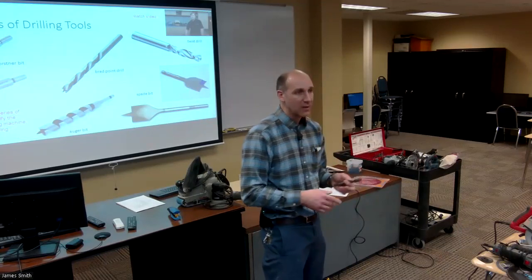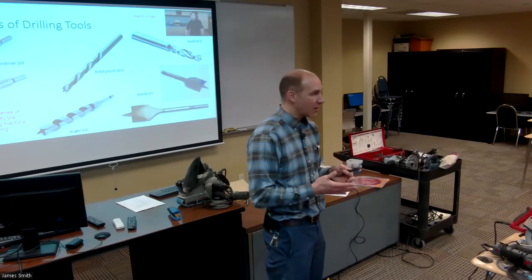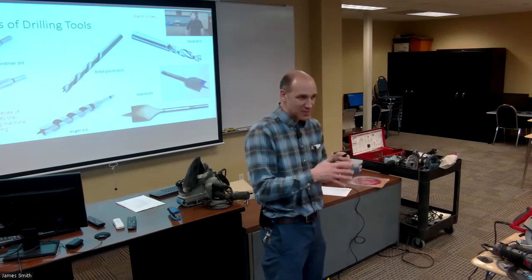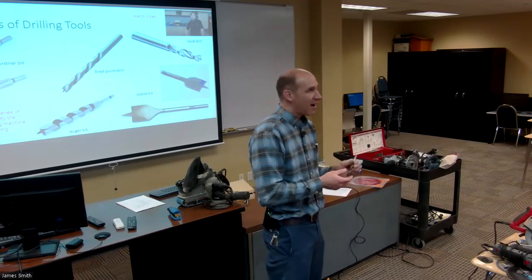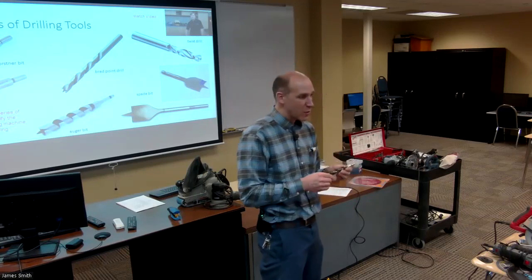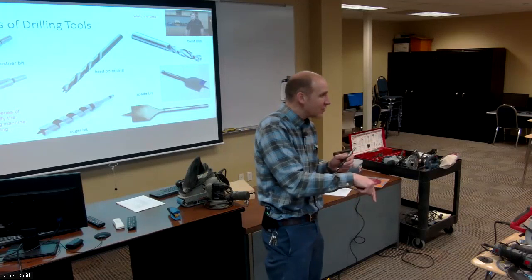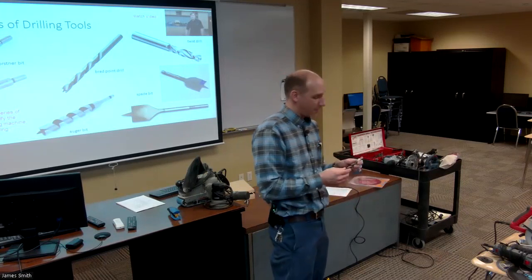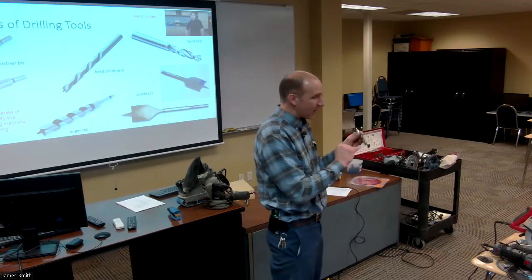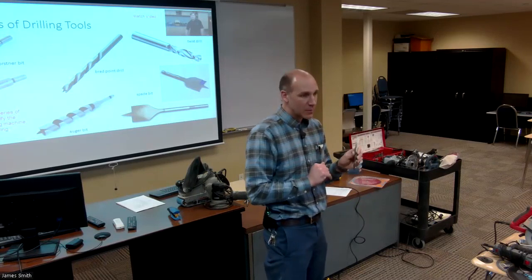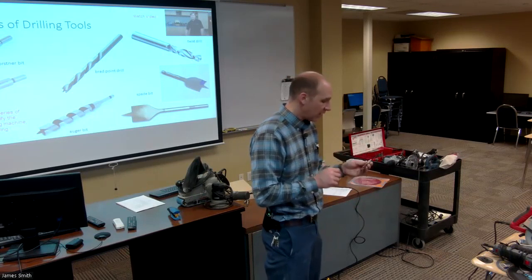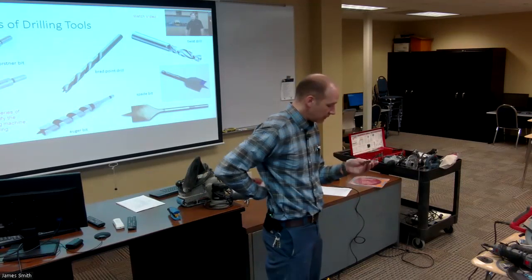You've got grain, and the wood is harder and more dense where the growth during the winter time is not as fast. Oftentimes, if you're just using a twist drill, it wants to go to that softer summertime growth. So having a brad point is pretty important if you want to drill very straight holes into really hard hardwoods.